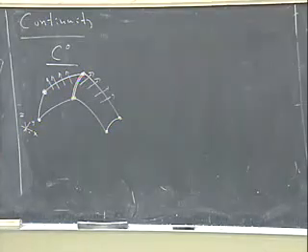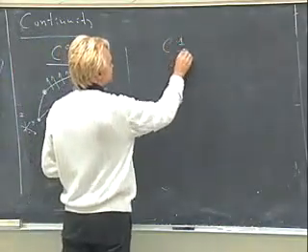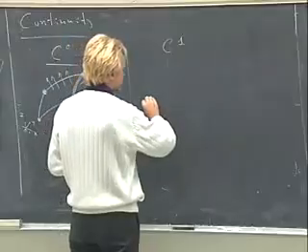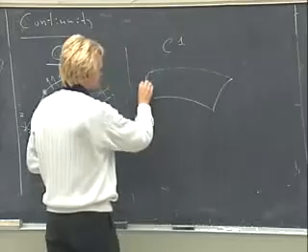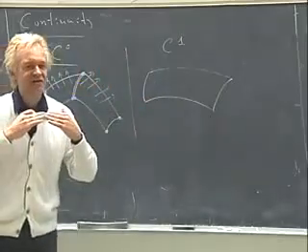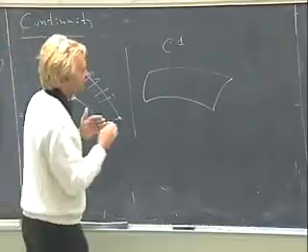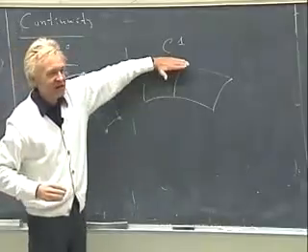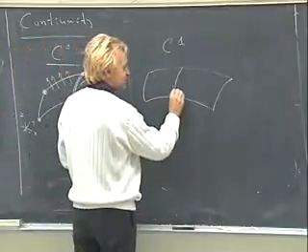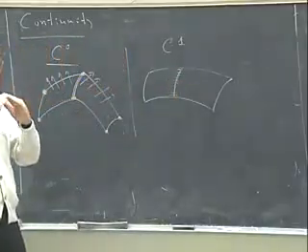Then you now worry about merging things in a smoother way, where the normal is the same, then it becomes C1 continuous. That means it would look like this. There are two patches coming together, but because they are joined smoothly, I don't even see that there are two patches, because they are continuously merged. Okay? So here is this shared boundary curve, but there is the same tangent plane, the same derivative across. They are joined smoothly.